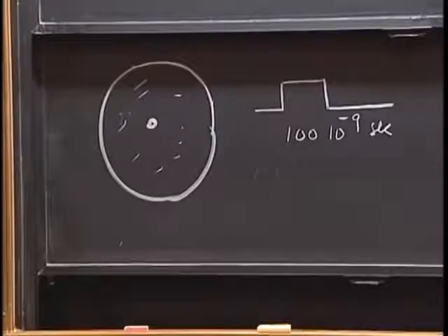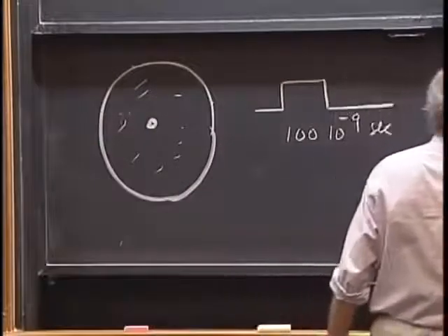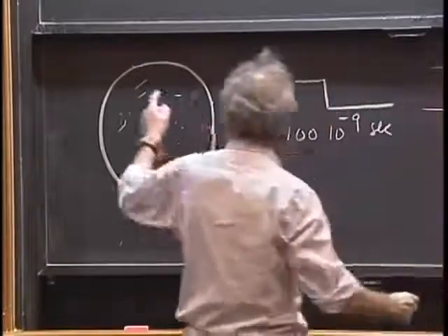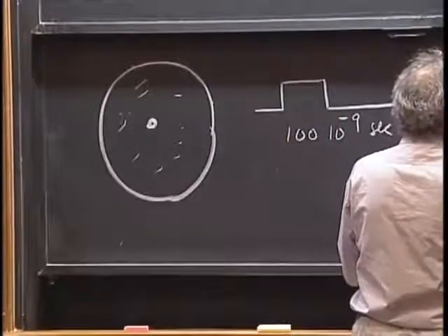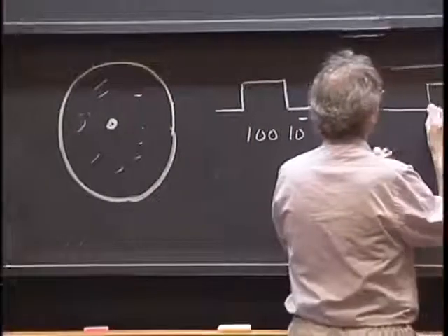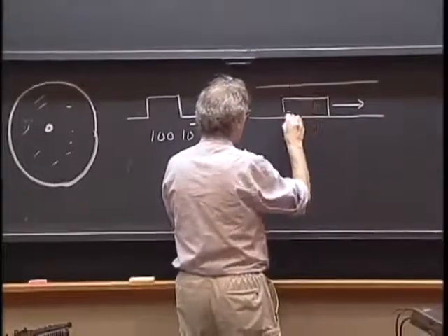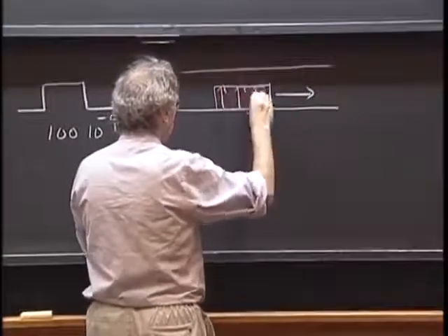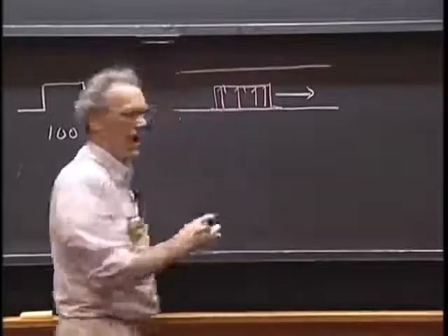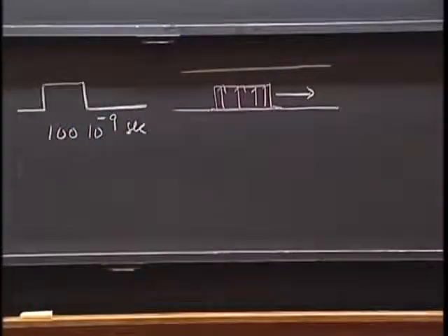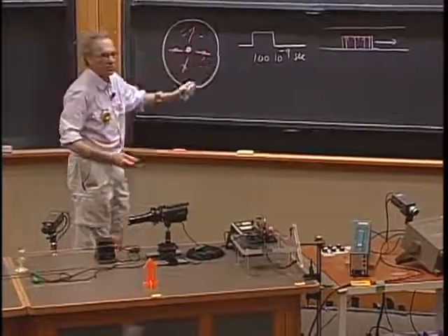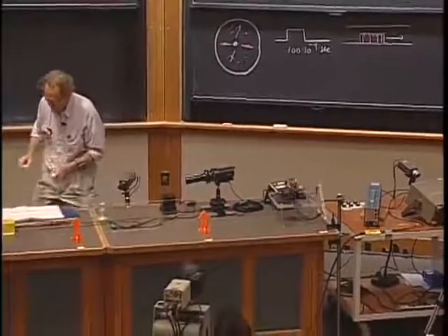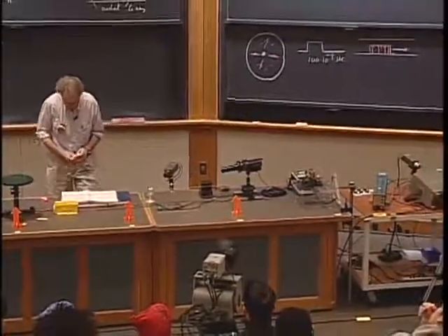In other words, if you look at the wire from the side, so here is the wire, and here is the shell, just take a cross section here so you see only that shell, then as the voltage pulse moves in this direction, you will see locally between the outer conductor and the inner conductor that E field, and it goes to 0 here and here. And that marches then with a certain speed along the wire. And so as that pulse passes, there will be an E field like this. But when there is no pulse, there is no E field between this and that. So in that sense, it's sort of similar to this transmission line, except the geometry is different here. It is a coaxial cable.